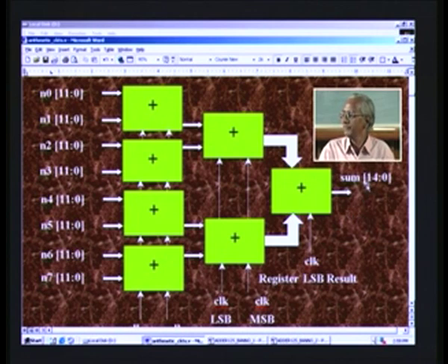and how 15 bits will be reasoned out right from here. We start with the 12 bits. When you add two 12 bits, it will generate a carry, that means totally 13 bits will be the result, and here also it will be 13 bits. So is the case here. When you add 13 bits, out comes a 14 bits result, and when you add 14 bits to 14 bits, the final output will be 15 bits. That is why 14 through 0 is put here.